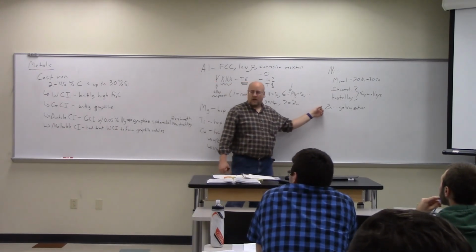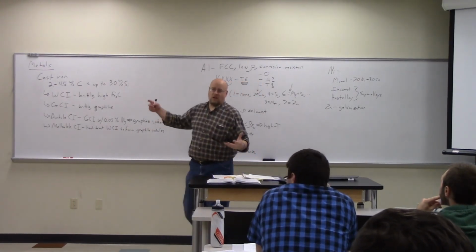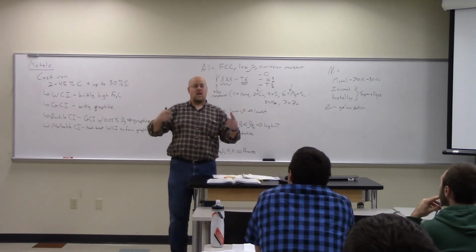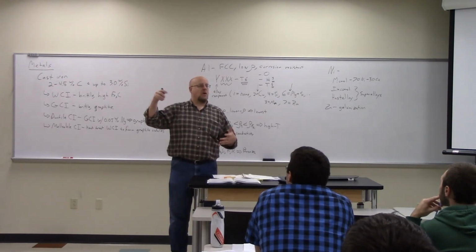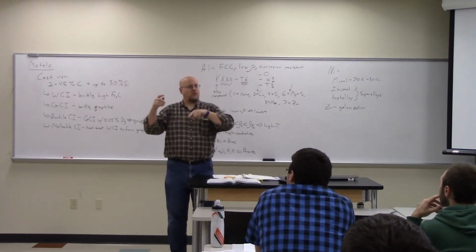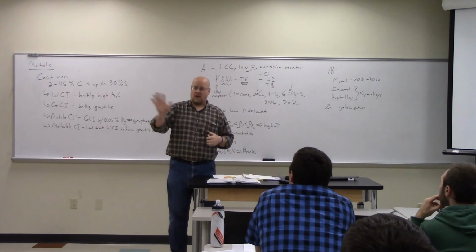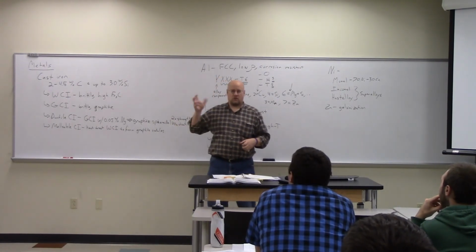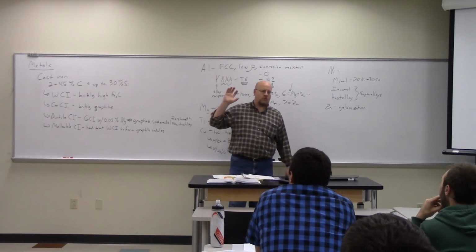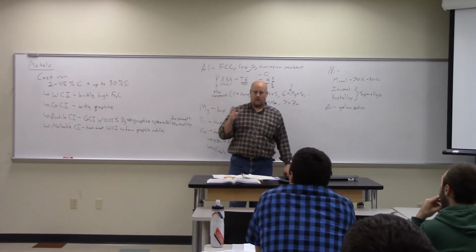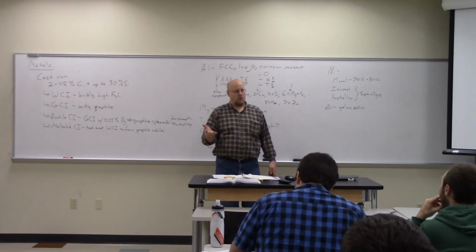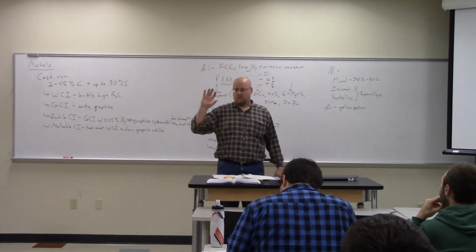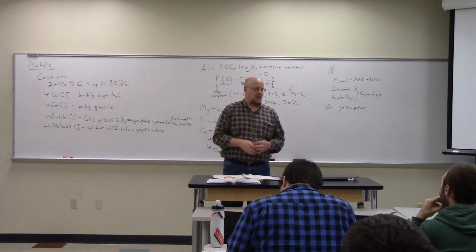And so zinc is used for galvanization so that if you have a scratch in your garbage can and the steel is exposed, it won't corrode at that scratch because instead the zinc around the scratch will dissolve and sacrifice itself for the steel underneath. In fact, back in the day, they used to screw or bolt zinc ingots on the bottom of a ship as sacrificial anodes to keep the ship from corroding. As it's sailing through the water, the zinc would dissolve and the steel would stay uncorroded.